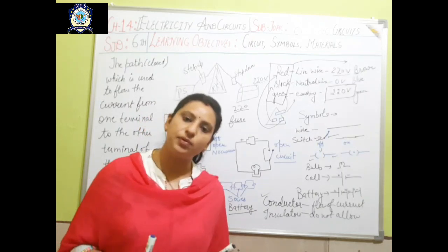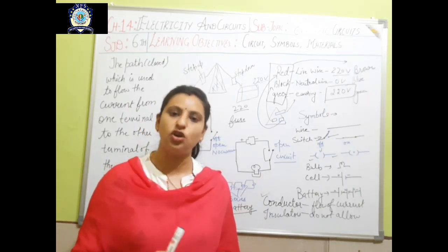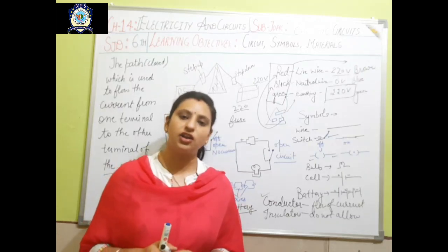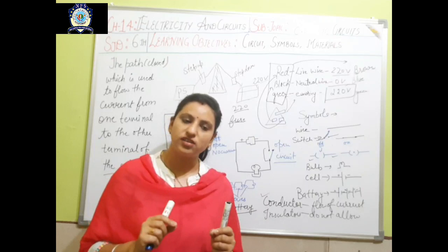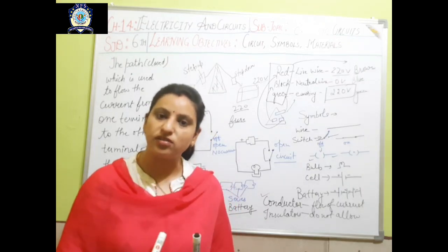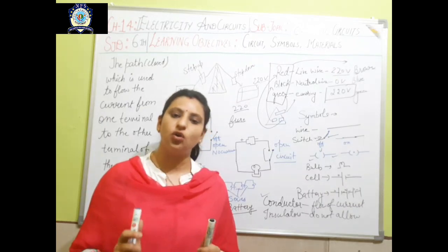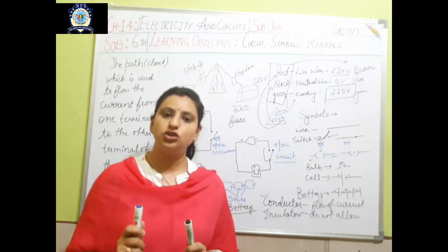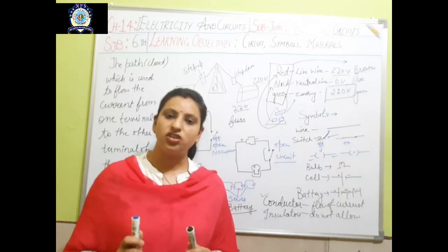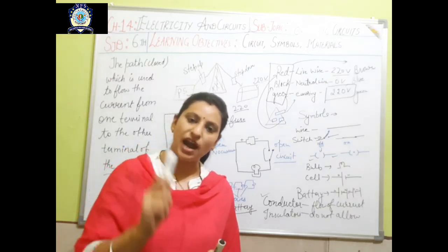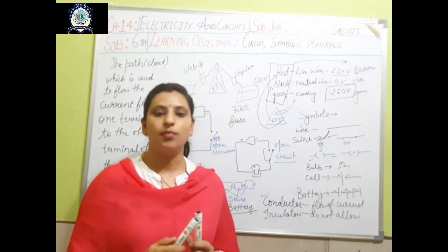And if you find any person who is having an electric shock, don't go and touch that person because your body is also a conductor and you might get the shock. So if you want to help that person, then touch the person with rubber hand gloves, or you can use a stick of wood or plastic or rubber, and give one hard pat on that part of the body which is in direct contact with the electric appliance.